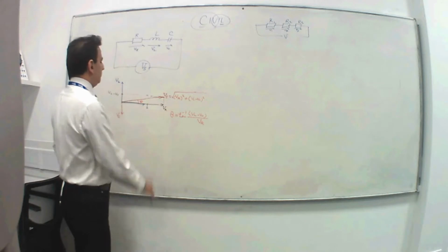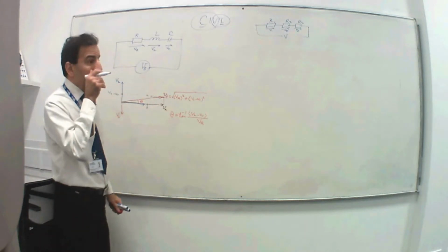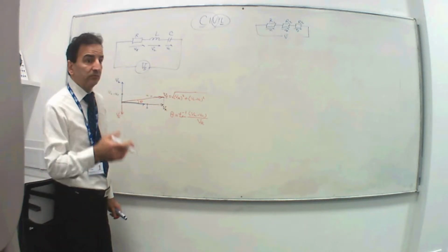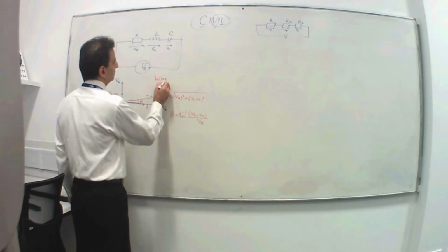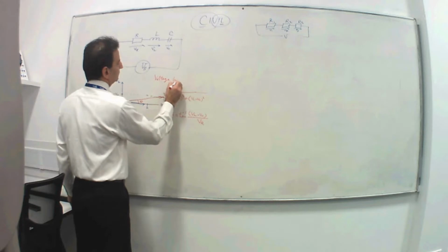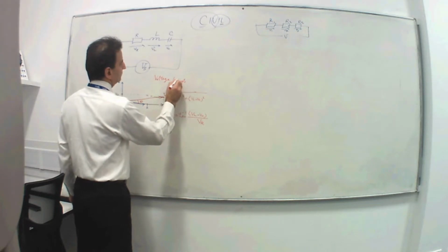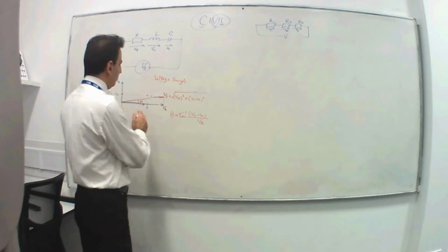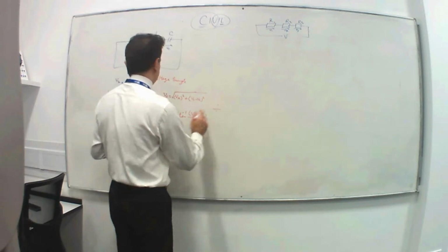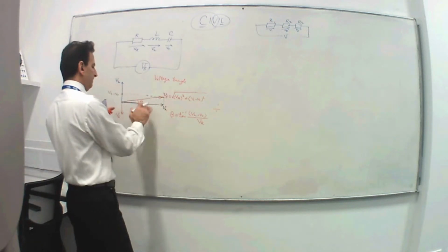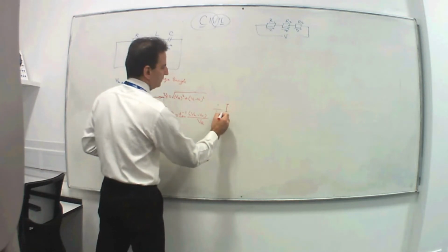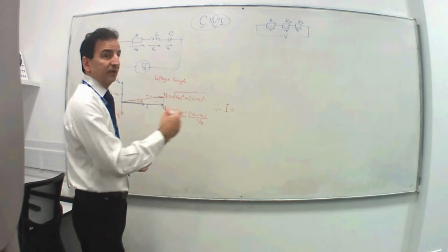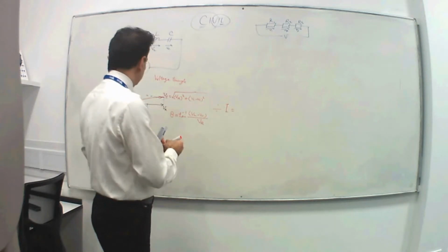We call this the voltage phasor diagram or voltage triangle. And then from that we said, if we divide the whole thing, all the phasor diagrams, by current, you get the impedance triangle.